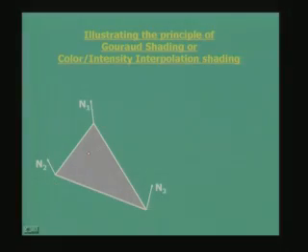I will roll this slide once again, which will be very interesting for you. So, what we are interested in, given a triangle as an example of a polygon, is to get the intensity of this point. So, first thing, calculate the surface normal at these 3. If these 3 surface normals are same, we are talking of a polygon not representing a curved surface in general. In that case, flat shading can be adopted. If N1, N2, N3 are all same, you will get I1, I2, I3 also as same, and then you can uniformly fill the polygon with the same color.